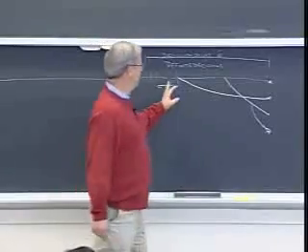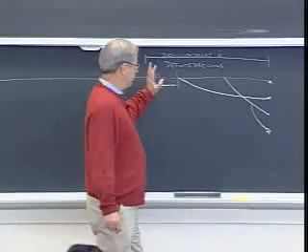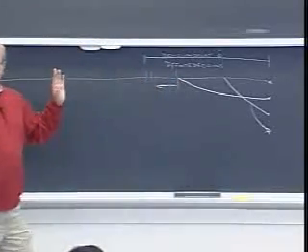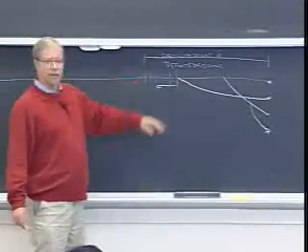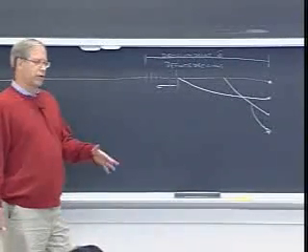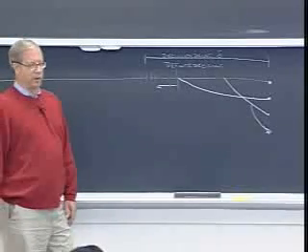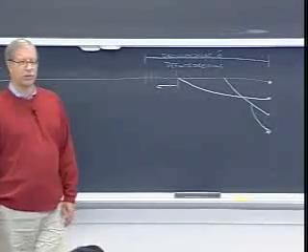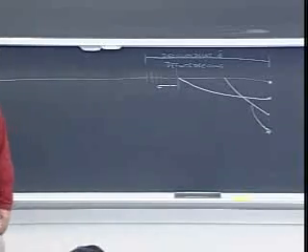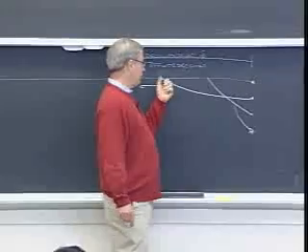Or you can make any decision you like. And you could be wrong. But you pick delta large enough so that the probability of this happening is very rare, and this just adds a little bit to your error probability. As long as the probability of making error because of this kind of operation is much lower than your probability of making ordinary decoding error, then you're going to be okay.